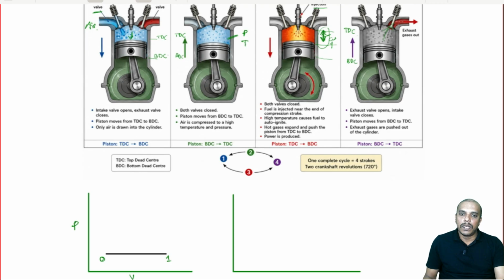So, this is our suction stroke, and compression is from 1 to 2, that is, the piston is again traveling from bottom dead center to top dead center. And remember, during this stroke we are assuming that the process is reversible adiabatic, because we want to supply lesser work. So, this was our constant pressure process, and this is PV^gamma equal to constant, alright. Now, 0 to 1 was suction and 1 to 2 is the compression stroke. Okay. Now, 2 to 3 is what?